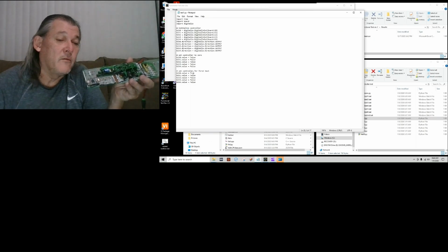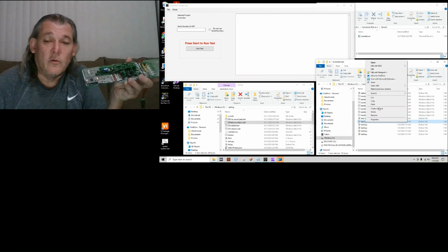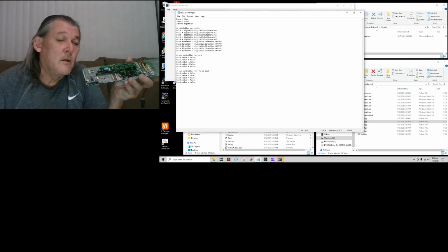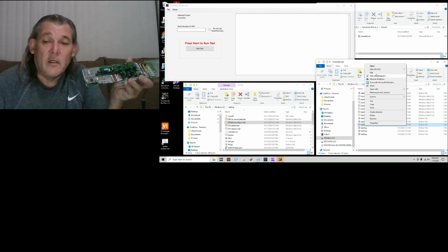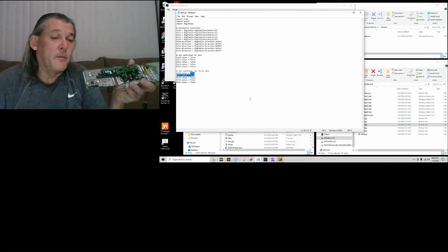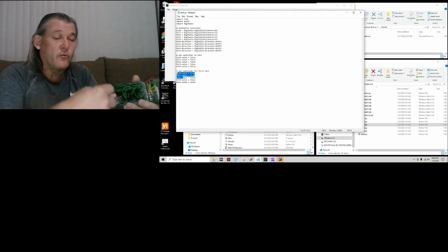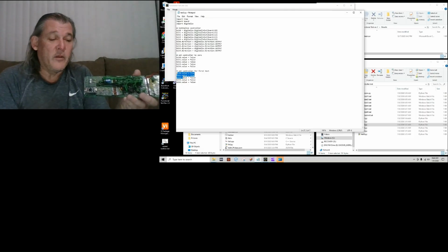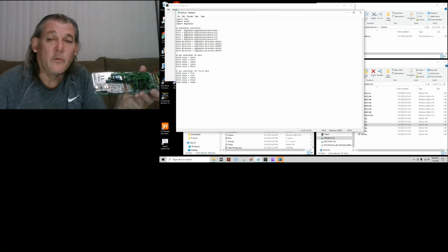I'm controlling the hardware by telling it what value I want here. Right here, I'm setting bit 0 to true, so that'd be test 1. Test 2 goes to the next bit, so this one is true. Test 3 sets 2 bits true right here, because I'm using bits 0, 1, and 2 to control this part of the hardware. The other bits go directly to here, so that's what you'll see in the next one.